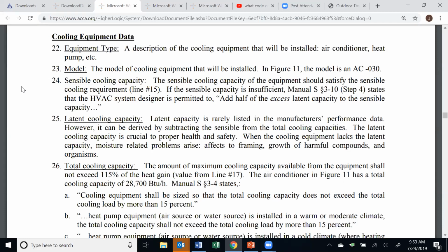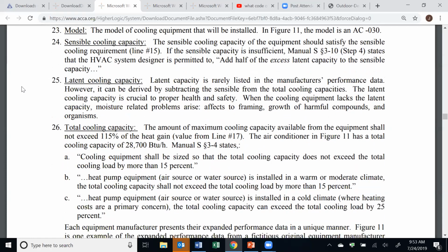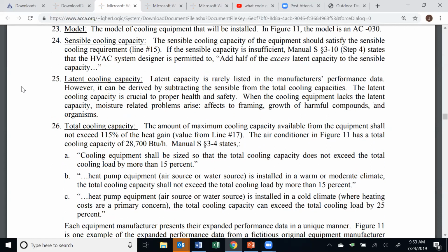Sensible, latent, and total cooling capacity. Just generally, when you talk sensible versus latent, a 101 difference, why it's important, and the total cooling, real quick. Well, absolutely. And so the sensible heat, the best way to think about that is what you would see if you were looking at your thermostat. What's that temperature? That's a sensible value. If you held out a thermometer, the value it read would be what we refer to as the sensible heat.